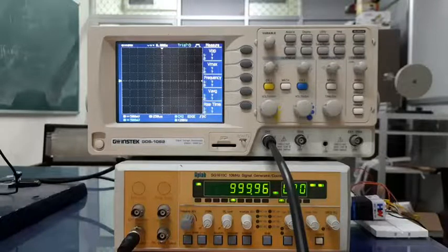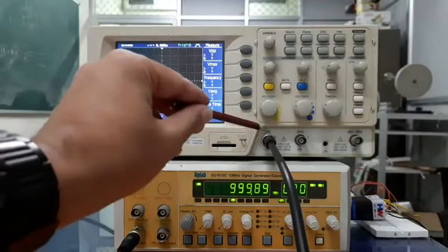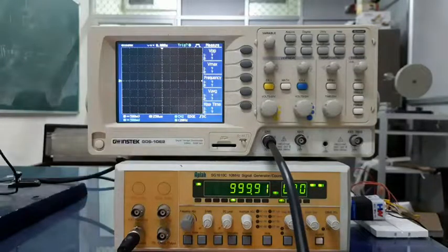Okay, so the first step is to know on which input we are giving the signal. For example, here, if you have only a single one, then it doesn't make a difference. But if you have more than one signal, then you need to identify which signal is going to which channel. Here we are giving the signal to channel 1. What that means is, if the input is going to channel 1, then the display should be set for channel 1 in the proper range, so that we can see the signal.